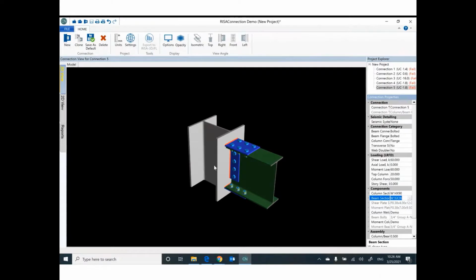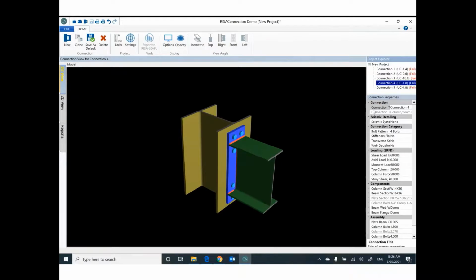Does that make sense? By the way, we have different technique. This one is common. You have head plate. This head plate is welded to this beam at this top flange, and this web and this bottom flange. And the head plate is bolted to the column.